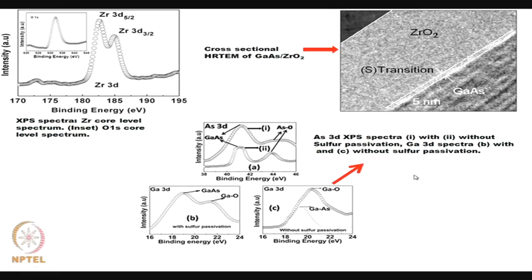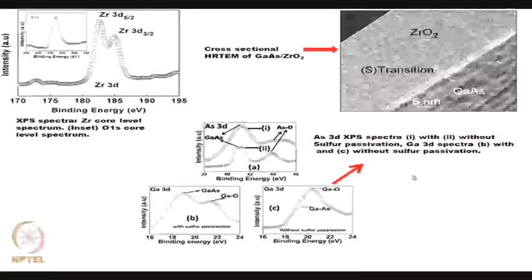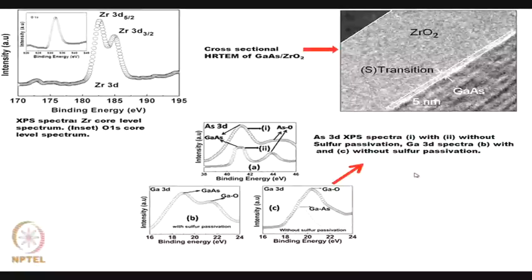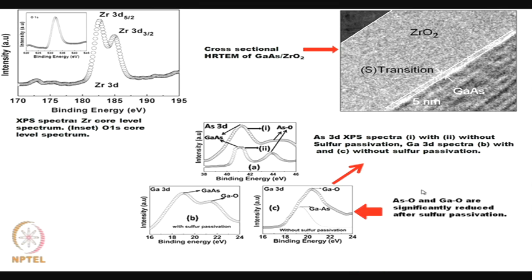So, the poor electrical performance due to these native oxides of gallium arsenide could be eliminated, the characteristics can be enhanced, and at the same time we find that this is the origin of the Fermi level pinning. So, there is a possibility that de-pinning has been obtained.